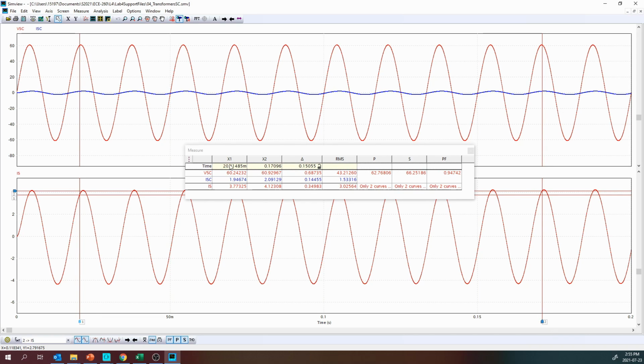And so what's going to happen is that you're going to change the value of the voltage until you reach your nominal current. The nominal current doesn't have to be perfect. It could be a few milliamps more or less, it doesn't matter, but close enough. And then what you do is you collect the RMS values for the voltage and the current, and you can also read directly from here the power that you are going to need in your table in the future.